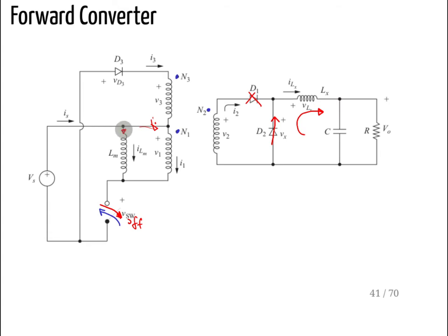That current is now charged up. It was increasing when the switch was on. It would like to flow that way, but now that path is closed, so it tries to flow in the other direction. If you carry some current in that reverse direction, D1 is blocked.